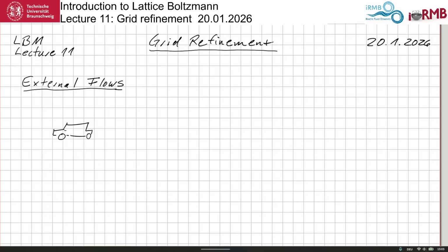There is a very annoying reason why lattice Boltzmann was able to do this while the others were not. I would always like to say that lattice Boltzmann is the better method, is so great, and so on. The reality is unfortunately different. The reality has really to do with these Cartesian grids. And this is a very stupid reason. Why is this a stupid reason? Because you can do control volume and finite elements all on Cartesian grids if you like.